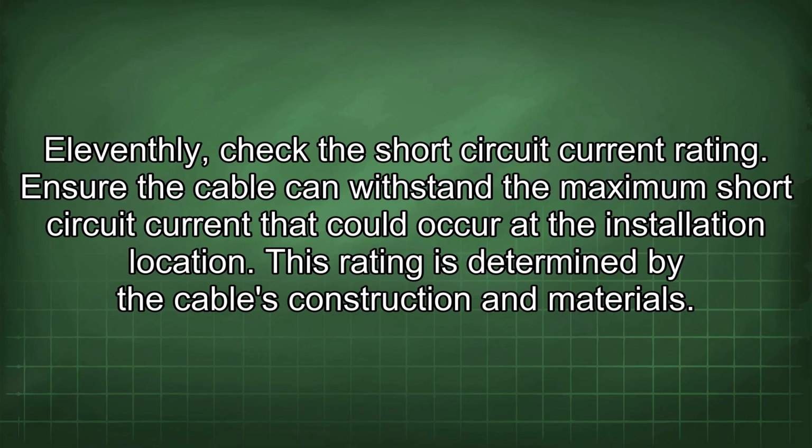11thly, check the short circuit current rating. Ensure the cable can withstand the maximum short circuit current that could occur at the installation location. This rating is determined by the cable's construction and materials.